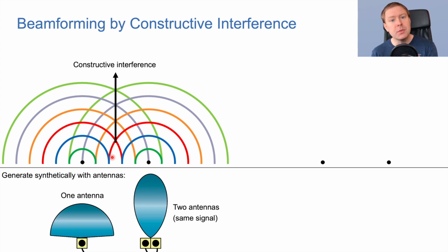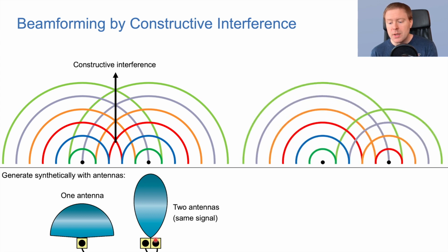If you would like the beam to go in another direction, we can do that. This is just how the conventional base station antennas with fixed directivities have been operating, by having multiple small antenna elements within the box and feeding them with the same signal. But suppose we let the right antenna here transmit a little bit later than the first antenna, the left one. Then we see that there are other locations where the wavefronts representing the same signal are intersecting.